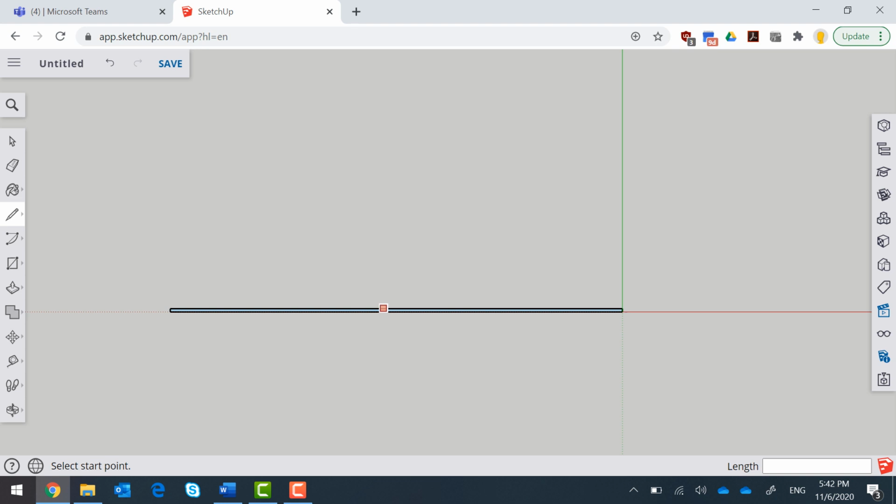So this is the first line of our bridge. The second thing, for instance, now this is only an example of a bridge that I'm doing here, but this should be applicable and applied for every design. I go to the midpoint. This is very good in SketchUp that it will give you certain points like the end point and midpoint, so it will be easier for you. I will go up, and for instance, the height of my bridge is 15 centimeters. Enter. Now, this time I will create the thickness for this middle member of my bridge.